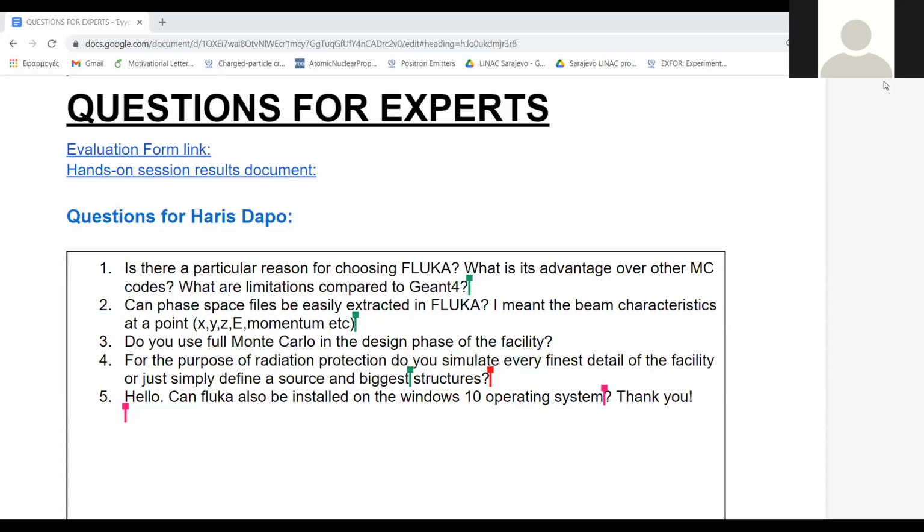Then, through other programs, you have to translate this into quantities like phase space and so forth. What you measure is emittance, and what you measure is energy deposition at a particular place. Then you can translate that through other data analysis, like ROOT and similar, into phase space information, because FLUKA is meant more to simulate a detector. So you have to think about how to detect phase space through emittance and then translate that back into phase space.